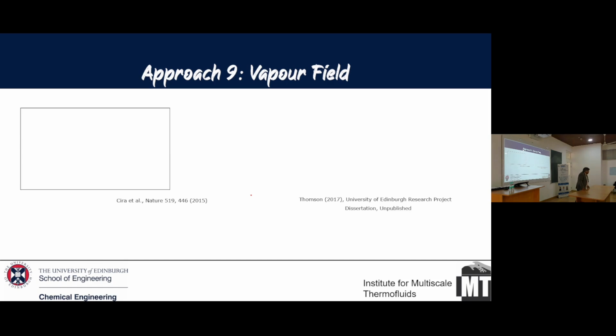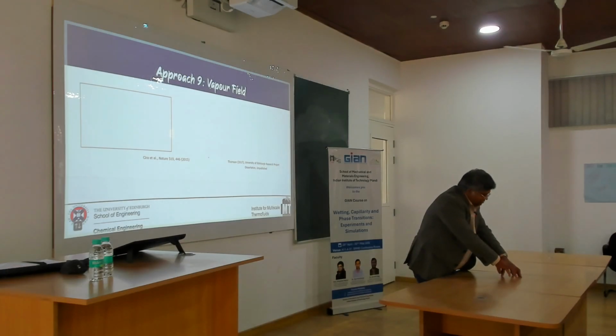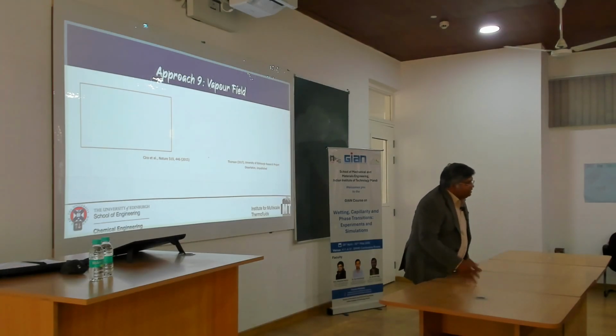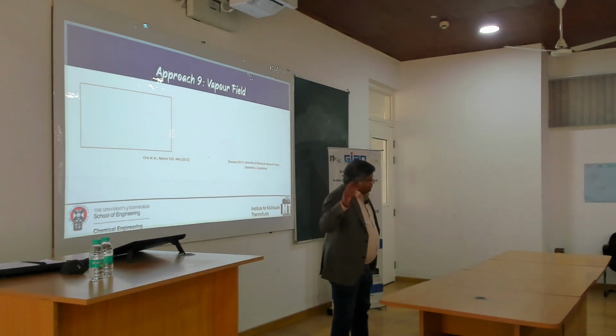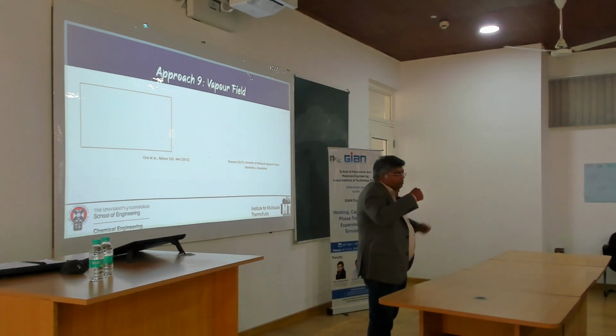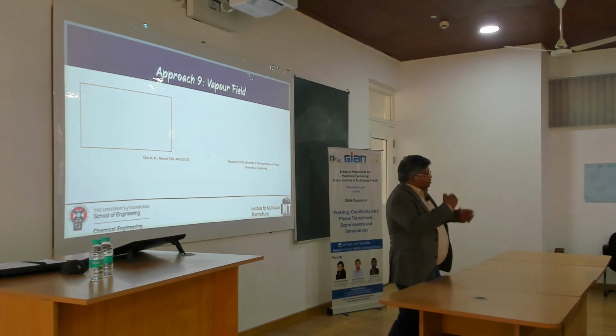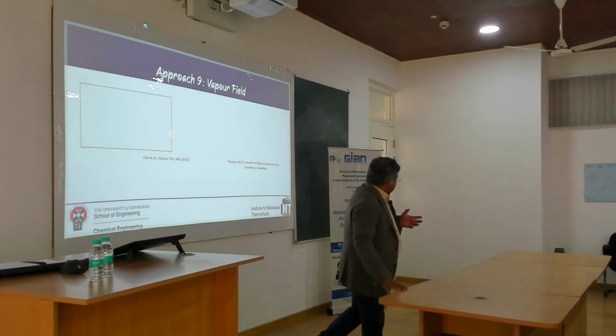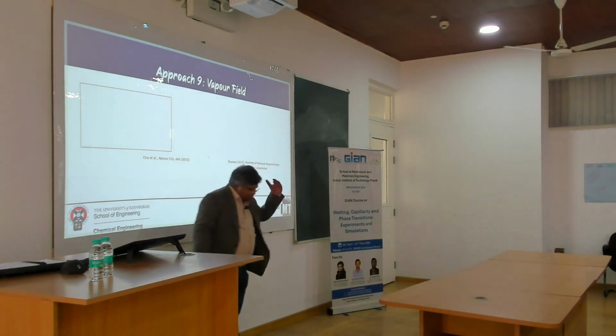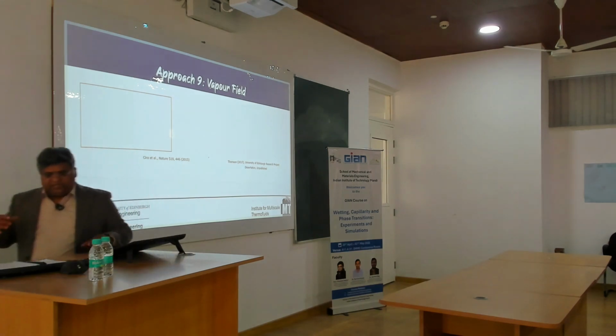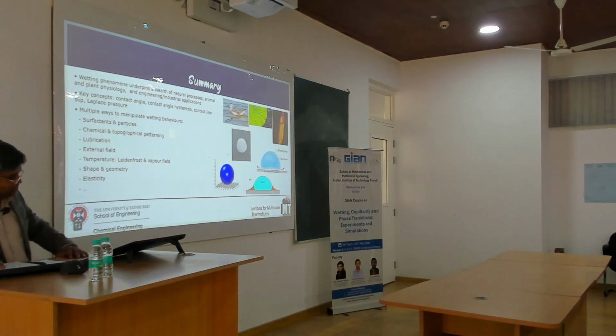Lithium bromide drop is absorbing the surrounding. Yeah. So this is pure water. This is lithium bromide plus water, and basically, it's just absorbing. So we did the modeling of that as well. It's published in JFM. So there is a competition between evaporation and absorption in those cases. Even if you heat it up, it won't get evaporated. There's a fight between the two. Okay. So it's absorbing. So this is one pure evidence of how vapor field can affect the droplets.